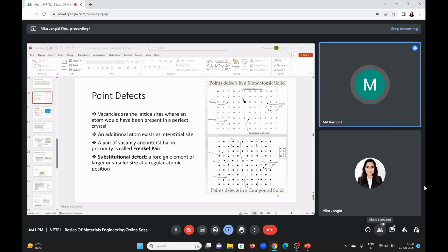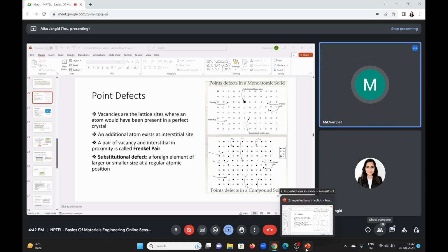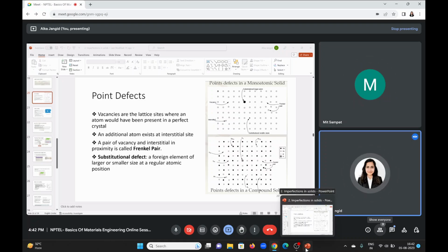So during manufacturing of any material, a stacking fault can generate by itself, because of vacancies as well. For example, during rapid quenching or plastic deformation, there is formation of vacancies in a particular area, and then there will be formation of stacking faults in that area. Can we do it intentionally? Yes, intentionally there can be formation because of plastic deformation. There is noted formation of stacking faults.